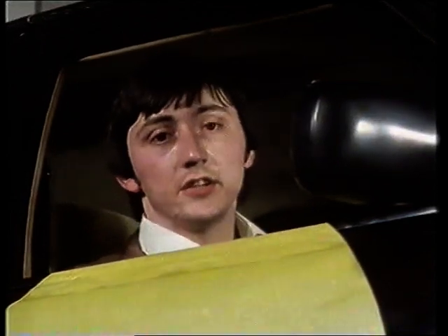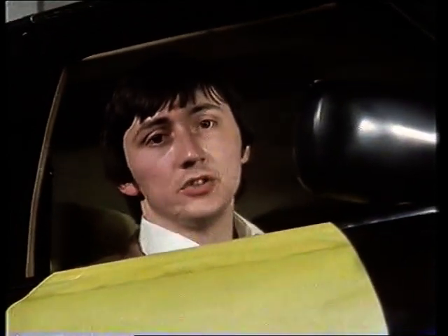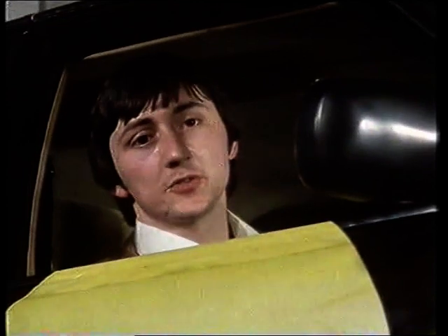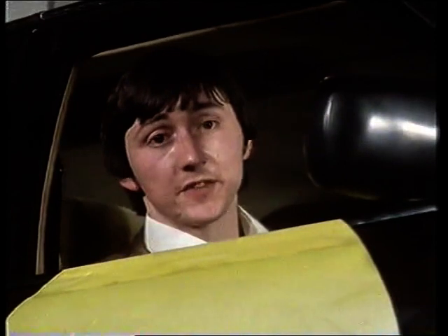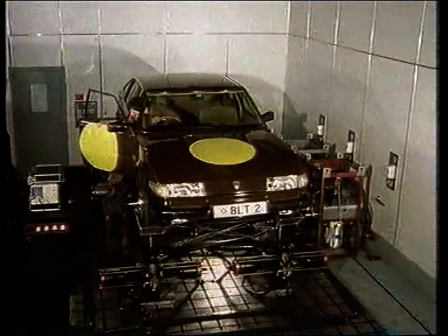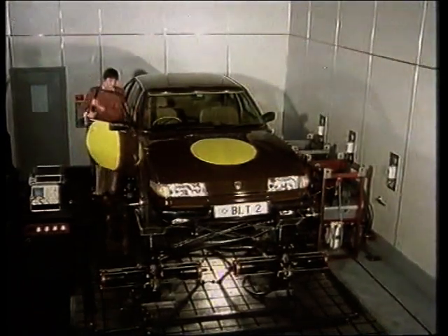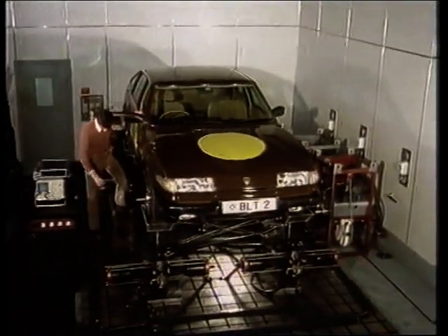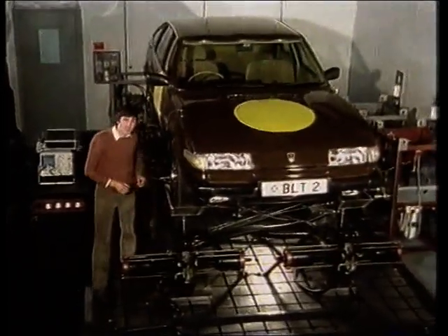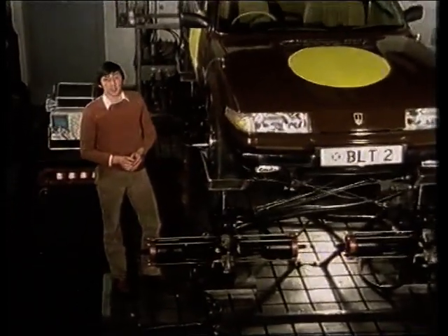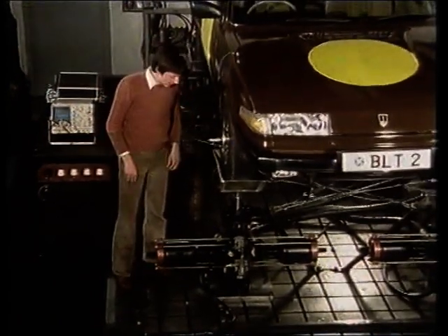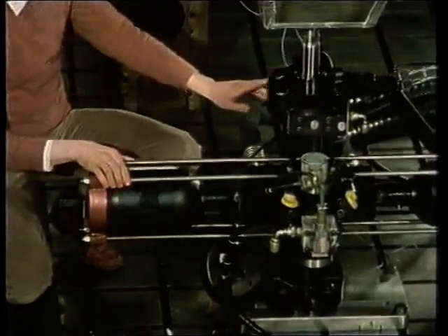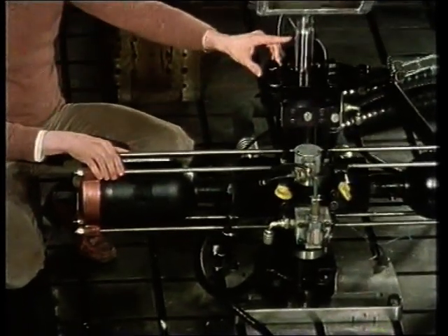Can we use the idea of a mass spring damper model to help us understand the difference between those two suspension systems? Well, firstly, we need some way of actually measuring the characteristics of the two suspensions. Motor manufacturers use rigs like these to study vibration isolation. Road profiles are stored on magnetic tape, and the tape is then used to control a flow of high-pressure oil to these actuators.